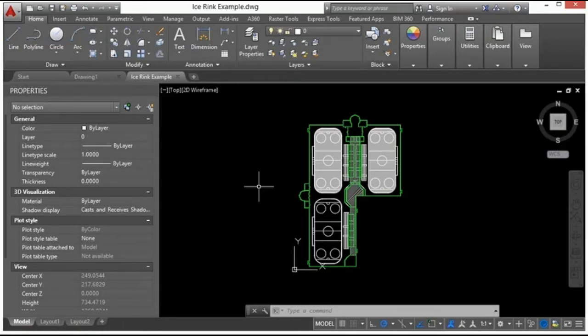This allows you to work from different perspectives simultaneously and to create different drawings. And when you're in model space, it gives you multiple perspectives of the exact same model. And what you do in one viewport, it's done in the other. It's very useful when modeling 3D objects or when working on very large projects. When you start your drawing, it'll have model space in it and it will have one viewport, just a single. Now you can work with as many as up to 4 or even more at a time. It divides your drawing up onto the screen.